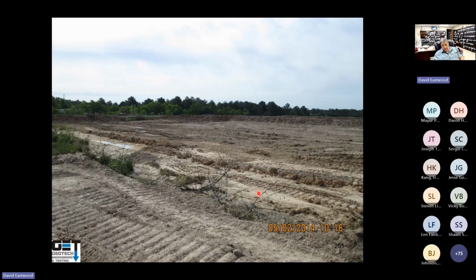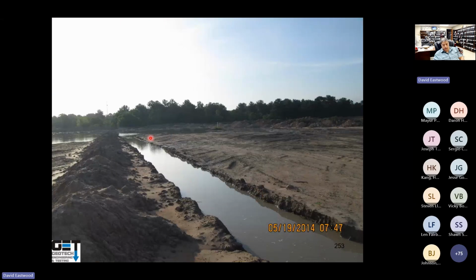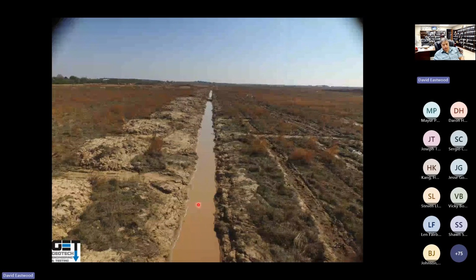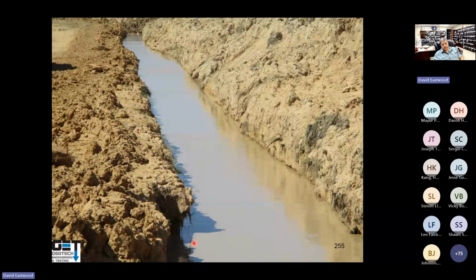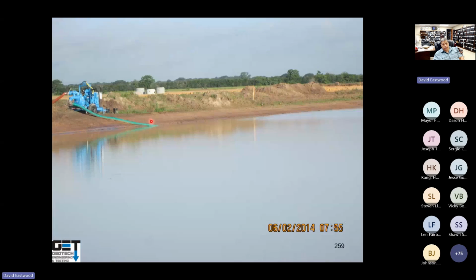Drainage, if your site is pumping, you can do bleeder ditches, kind of drain the sand and silt. You put this in a grid, about 3, 4 foot wide and 3 foot deep. Drain the sand and silt. You take it to a detention pond, and then you pump the water out onto the neighbor's property.